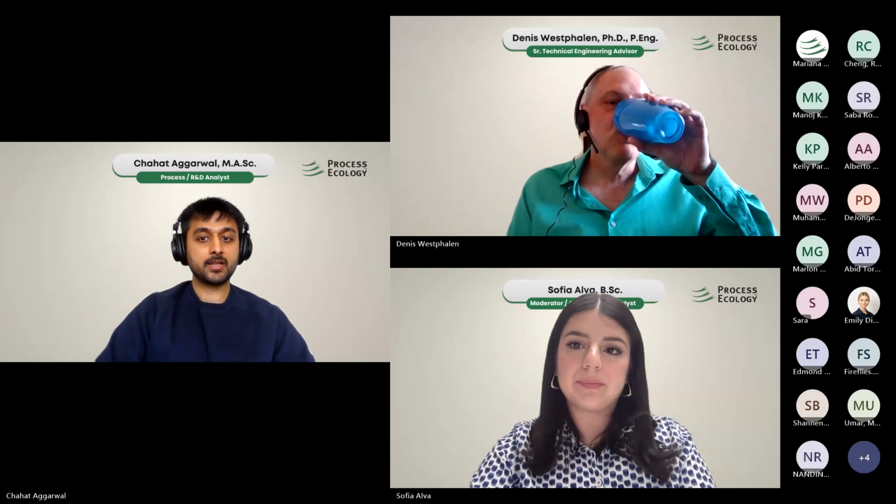So, Jihad, how can we validate that our simulation model is correctly tuned to plant data? Are there key performance indicators to look for? Yeah, so we want to track the relevant variables, like I said, the product specification, key component composition. But importantly, there are also key acceptance criteria for these products based on ASTM methodology.